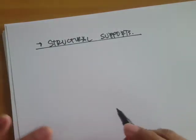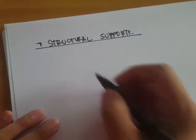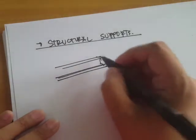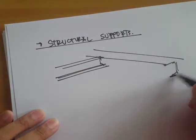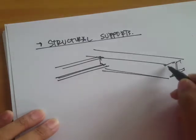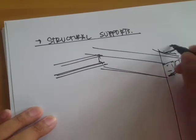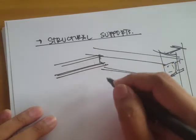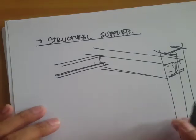Now recall that the structure is composed of many structural members that are connected in some way or another. So for example, a beam, let's say a steel beam, rests on a girder, a much larger beam, and then the girder rests on, let's say, a column. So this connection or this joint must be idealized, and that's what we call a structural support. So how do we model that?